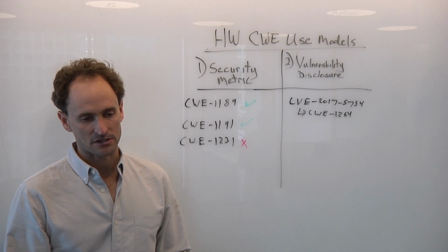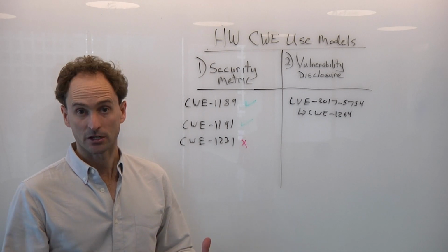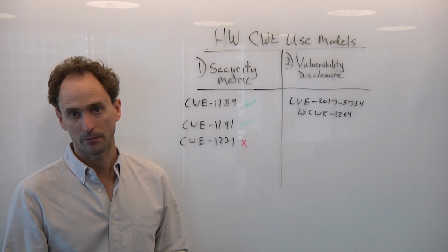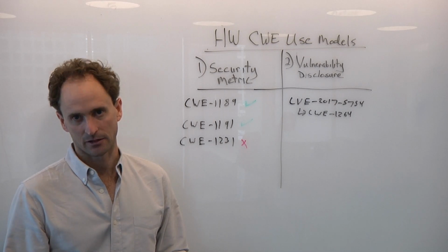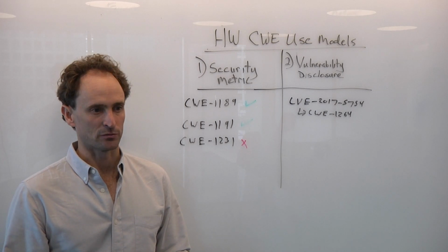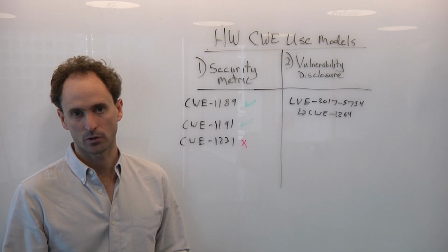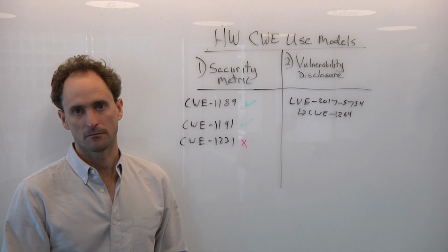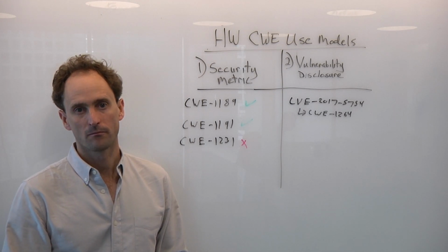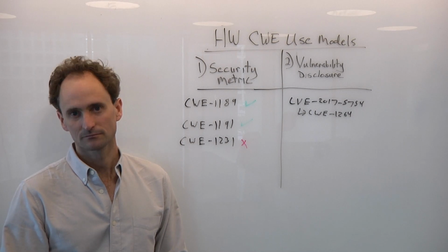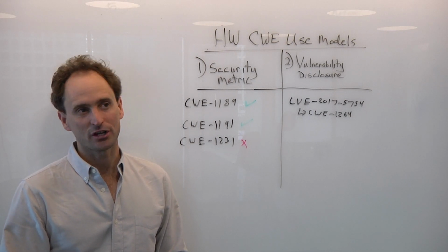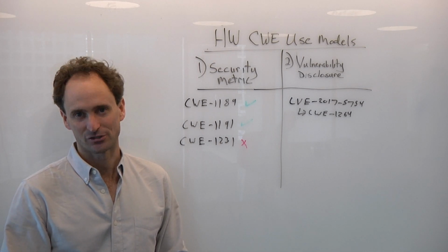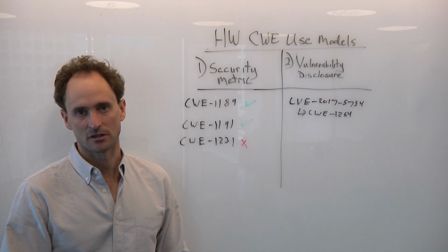So I think it's important, as part of the security program, to assume that vulnerabilities are going to come up, and you have to have a way of reacting to that. Whether that's a plan to actually replace the chips or a plan to issue firmware updates, basically an incident response plan as part of your organization so that you can manage those things because they will come up. And this is a real-time update that you need too, right? You could obviously RMA the chip and get it back and do the update. Remote updates have their own issues on top of that as well, but that's obviously the most economical.